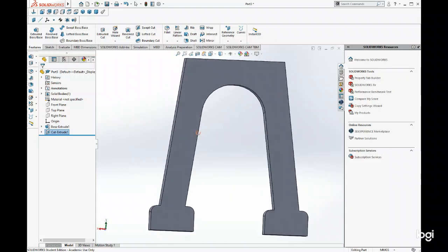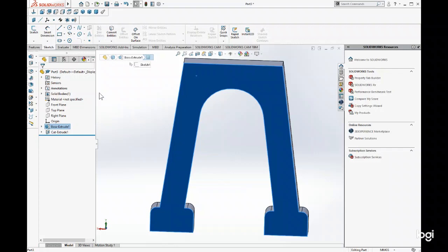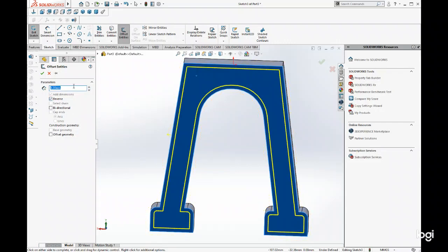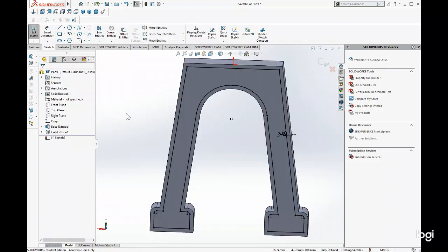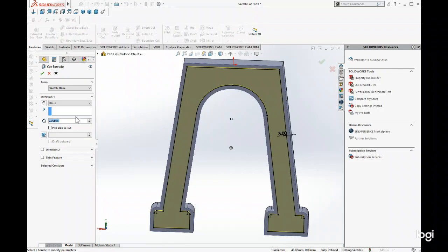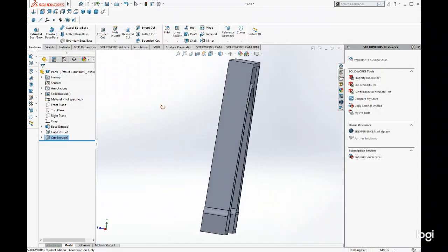Yes. So I'm going to flip it on the other side, create a sketch, and do the same thing on that. And I may go a little fast for you, but you can pause the video and do it at your own time. Click there, extrude cut, 2 millimeters. I like it. Now it's done on both sides.